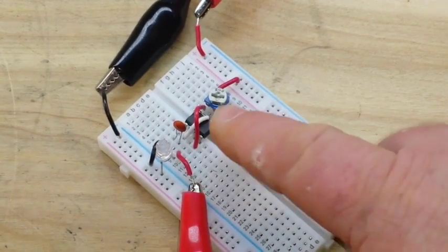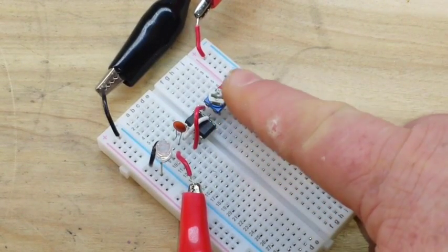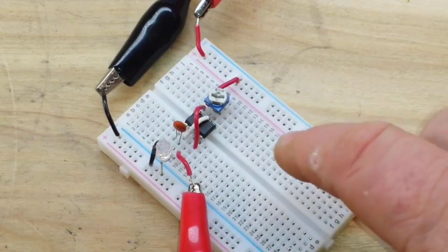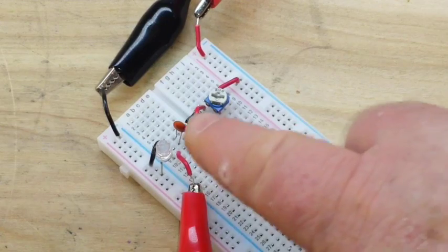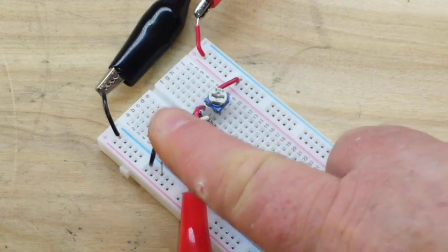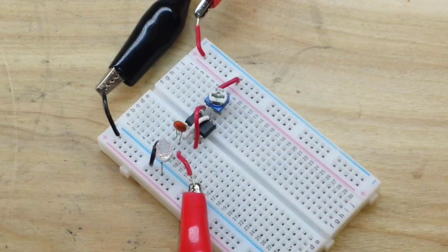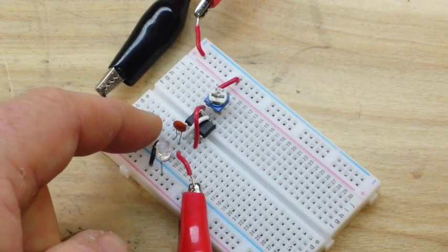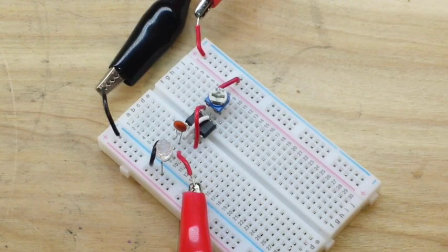So anyway, my super simple 555 timer circuit: you need a potentiometer. The value really doesn't matter. A 555 timer, a capacitor, and an LED. In fact, you really don't even need the LED for this. It's basically just an on indicator. With the values we have here, this is a 20K potentiometer and a 104 cap. We're going to get a frequency of about 700 hertz or so.